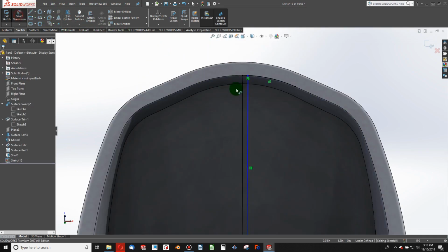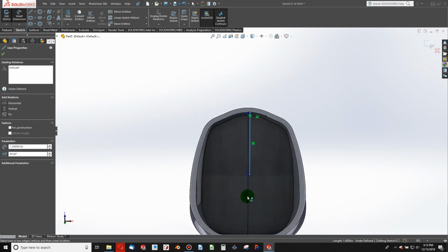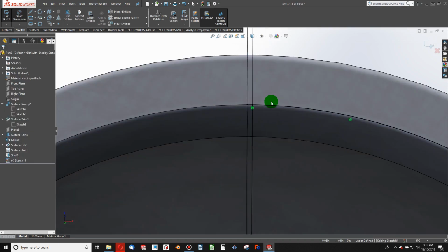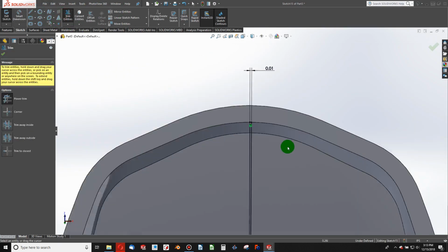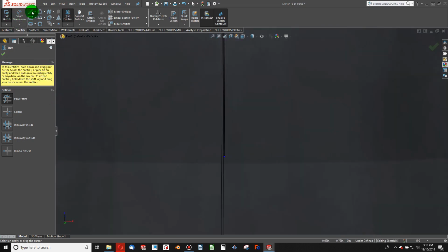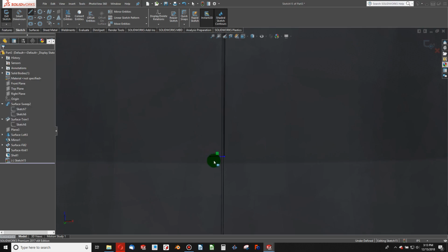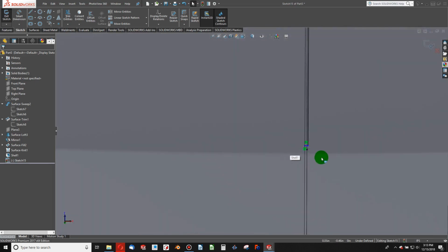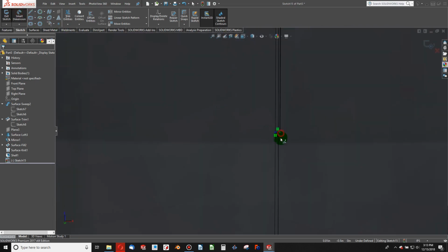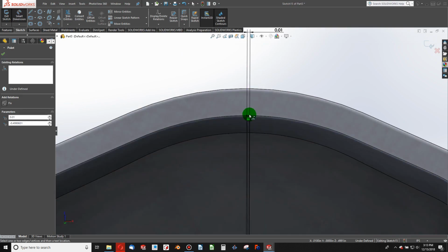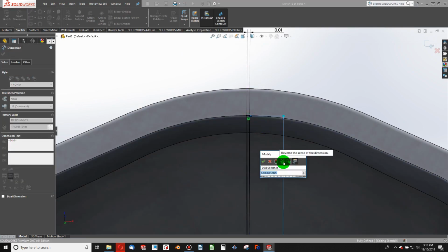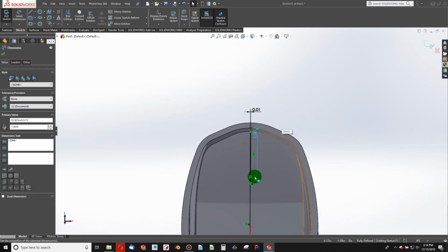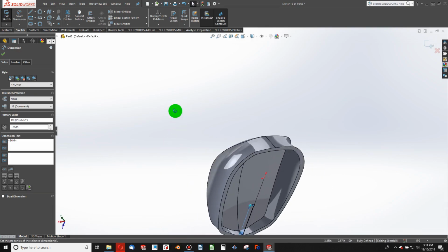Now I can dimension this line to be off of our center, say 10 thou. I'll make a trim, and then I'll make a line that terminates vertical to the origin. Now I simply need a distance for this slot to last. Let's go with, I should say 1 inch and see how far we go. That seems like a reasonable amount.